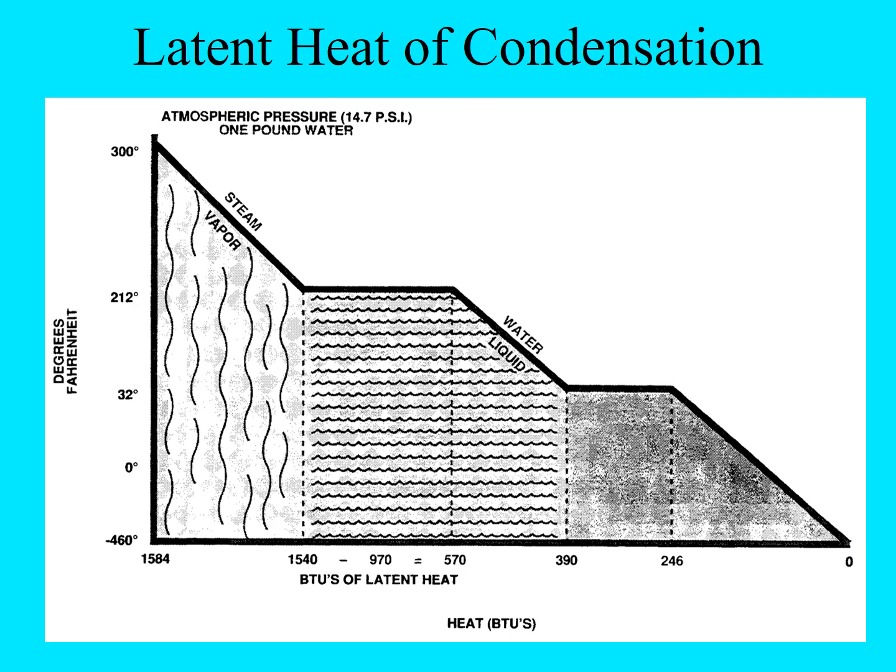So here's the graph of latent heat of condensation. This is just the reverse of vaporization that we looked at in the other graph. So if we have that steam and it's heated above 212, we have to get it cooled down. So we're going to have a sensible heat change from up here to this point, okay? So once we get it down to 212 degrees,